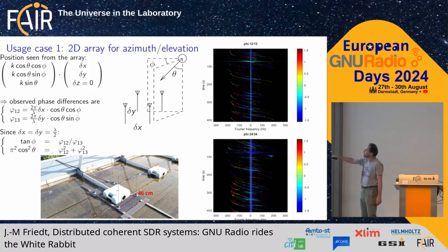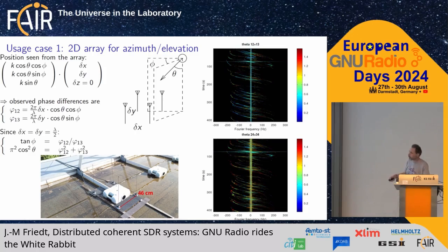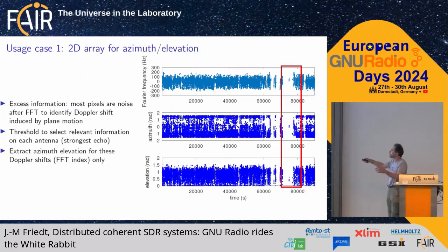So you can very easily calculate that from your phase measurement between the 4 antennas, you end up having azimuth and elevation. So we've got here azimuth as estimated by 2 of these antennas, we've got elevation as measured by 2 of these antennas, and then you can end up plotting for the whole time what is the evolution, so the velocity as a Fourier frequency, azimuth and elevation. Now this is such a crowded chart because there are so many planes flying over our university, there's nothing you can see with it. Except during the night.